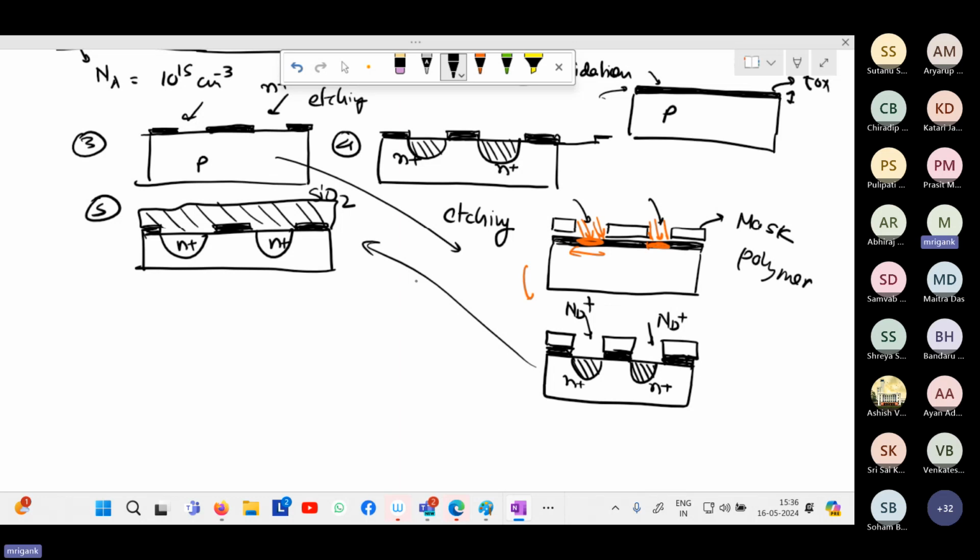If you create a small MOSFET circuit and you want to fabricate it, ultimately, in the fabrication process, you will have a bunch of transistors sitting in one single chip. Those transistors need to be fabricated at exact locations. Connections between them also need to be fabricated at different locations. That will be done with the help of these masks. So for every fabrication process, these nanoscale, very accurate masks need to be fabricated. Their alignment needs to be made. The etching process, doping process, oxidation process, etc. need to be carried out step by step to create all these MOSFET circuits in the silicon.